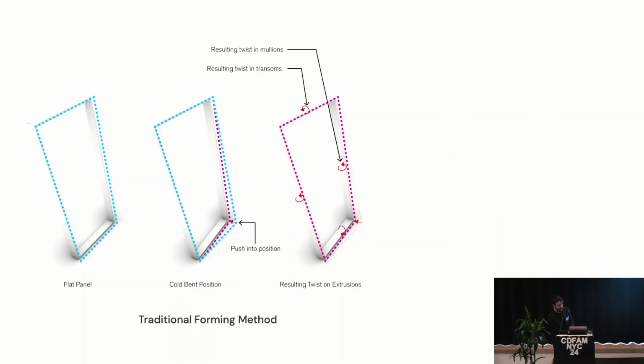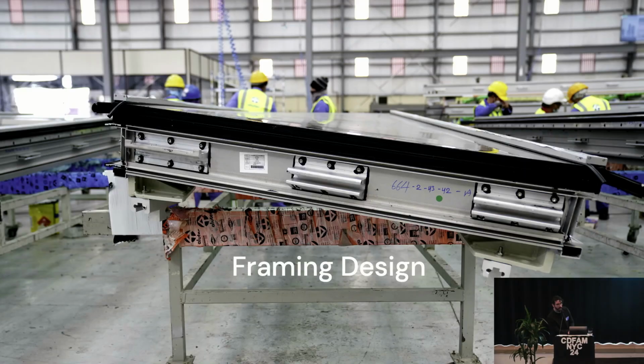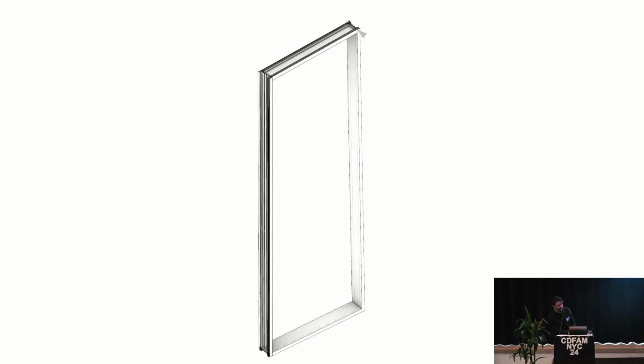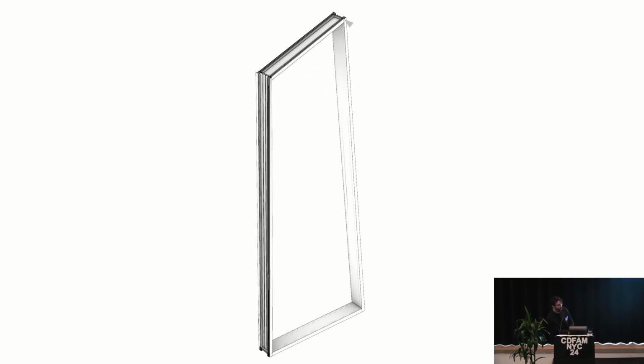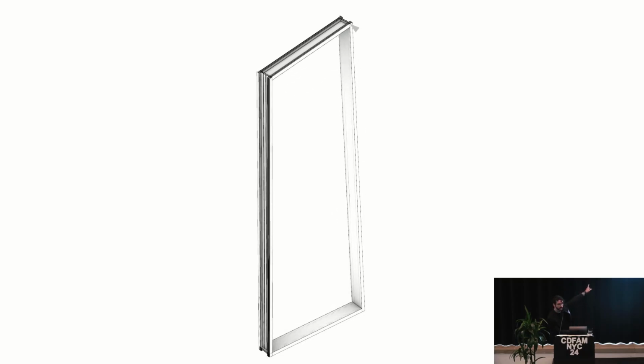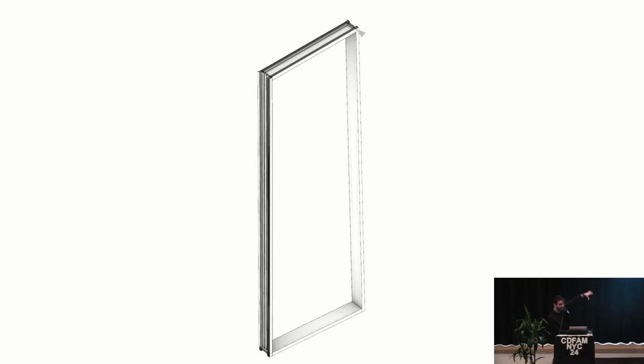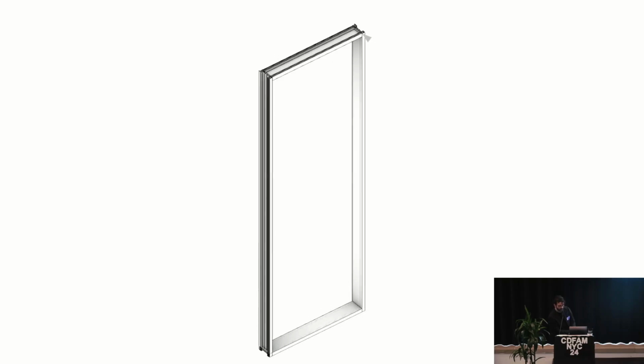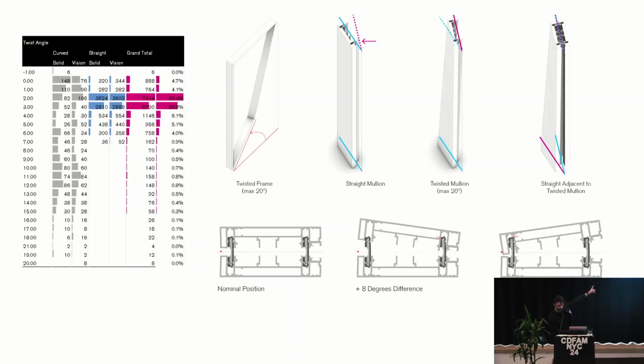So we decided to build the panels in 3D. That way when it gets to site, it just goes up on the building. There's other considerations like when you push on that 4th corner, even though the one that's near us is fixed, it's also twisting. So every other component is twisting in the panel. That causes problems with the engagement between adjacent panels, what you see down here on the bottom, the kind of interface between these things.